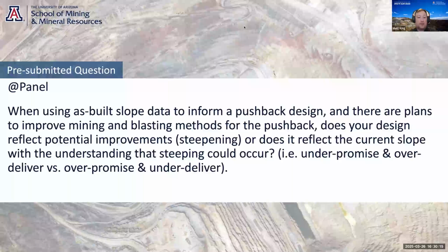Mine planners love to steepen designs, but they really do not like to flatten, because all of a sudden people are looking at it as a loss. You're leaving ore behind and whatnot. So if instead you give them a base slope that you expect is achievable, then anything they can do better than that is a bonus. And if you're operating on your steeper design and, as Carl mentioned, you hit a surprise and things aren't going well, you can always take a step in and go back to your original design and continue from there.